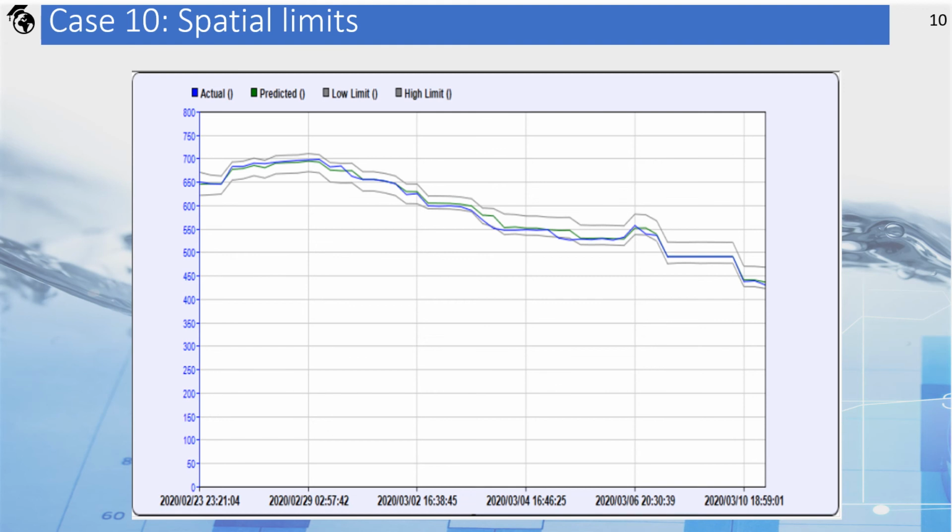In the example above, we can see a sample of conductivity. A 300 micro-Siemens conductivity value at one station could not change substantially within 3 to 4 kilometers at a destination station, unless something or someone tampered with the water. Any deviation from the boundaries indicates that something happened to the water in the passage between the stations.